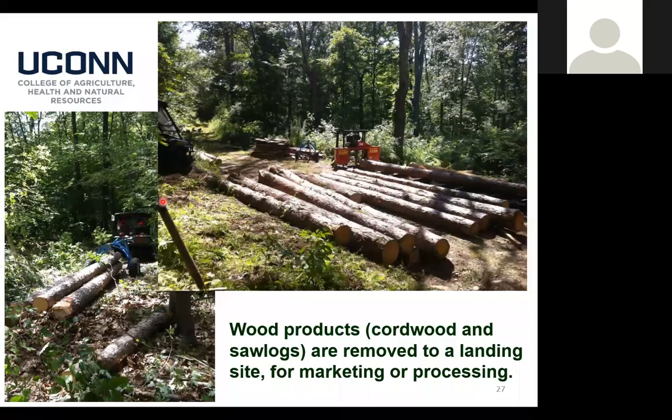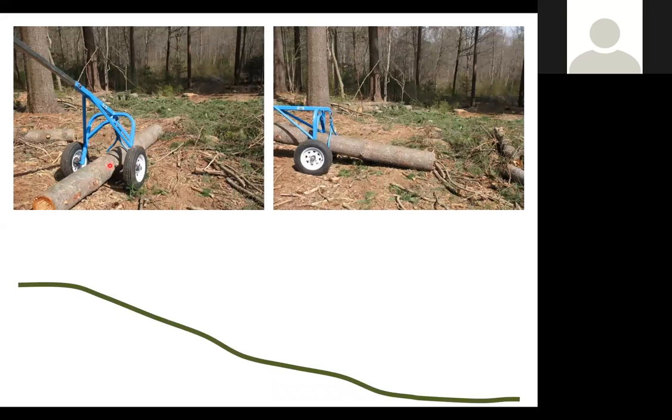I just wanted to point out with these arches, you have a couple of options. In this photograph here, notice how we're picking that log right up at the center. And if you find the balance point, you can get that log right off the ground entirely and move it around. You saw that Mike did that with that hickory log. If you pick it at one end or the other, you'll have one end on the ground with some drag.